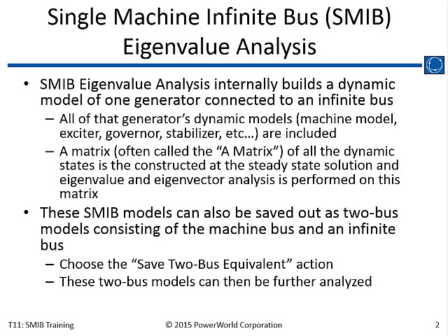But the idea on the single machine infinite bus eigenvalue analysis is we don't do a full modal analysis on our system by calculating this large A matrix. That's something that's known as small signal stability. PowerWorld doesn't do that. And I think that's kind of falling out of favor a little bit as we get into other analysis techniques.